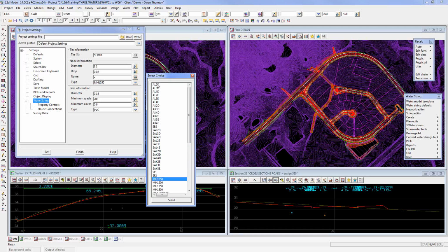Okay. In the case of all of these type A gullies, the second character begins with an L or a K. That stands for lip inline or curb inline configuration. And the reason we have to discriminate here is because they have different set-out points and different inlet capacities, and potentially different symbols as well if you're talking about plotting. The third character is a 2, 3 or 4. That's the size of the lintel, the 2.4, 3.6 or 4.8 metre long lintel. Again, straight off the standard drawing set from Brisbane City Council. It's your small, medium and large lintel. And again, different lintels have different inlet capacities.